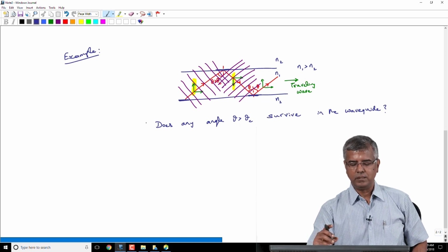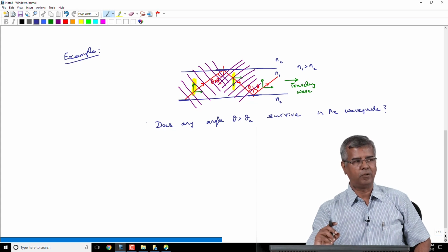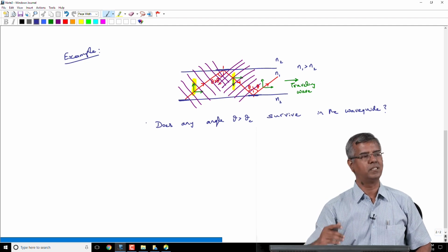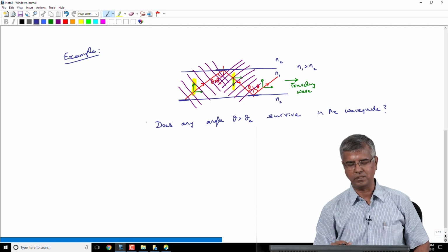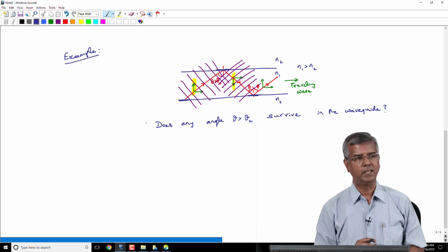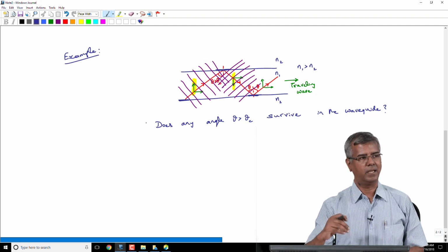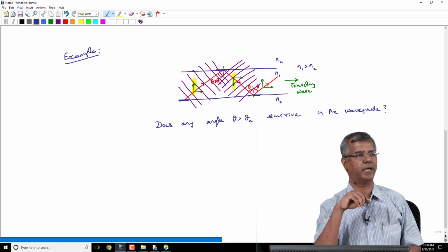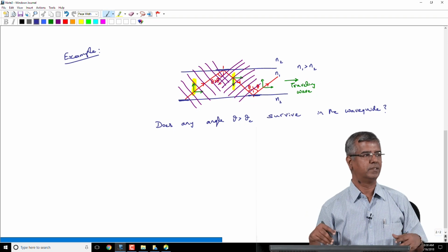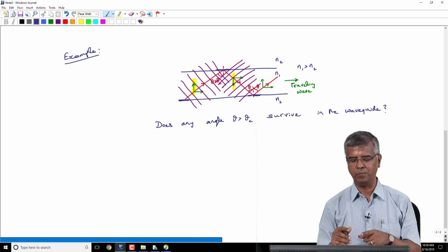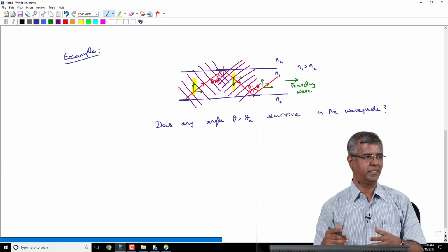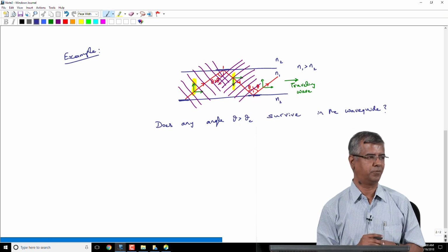In other words, the electromagnetic field configurations that I am satisfying in this structure are symmetric about the center, and have got to be consistent on either of these boundaries. One way of saying consistency is that if I am having constructive interference over here, I should have constructive interference over here as well. Okay. So, over the round trip, I should have the constructive interference criteria. If I am looking at the incident wave and the reflected wave, the phase that I have accumulated between the two has to satisfy the constructive interference criteria.